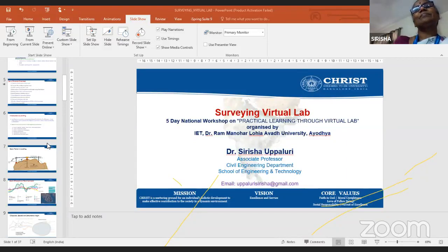One more question. What is the chainage? This term is used for road survey, and how and where is it taken while doing the leveling survey? Chainage means the distance from one staff position to the other staff position, between stations. Station means, in leveling, the staff location is called a station. So between two stations, that is a chainage. Back side to the intermediate side, or a foresight, that is the chainage. Or intermediate side to the next intermediate side, that is a chainage.